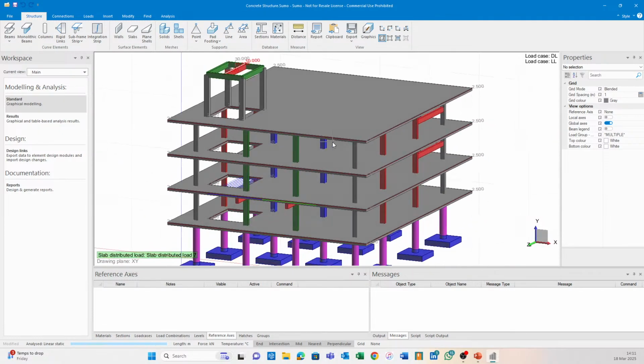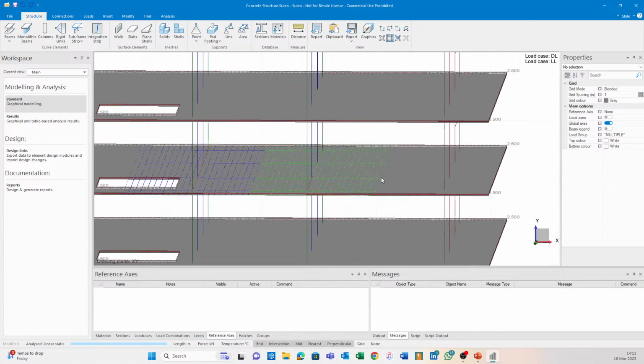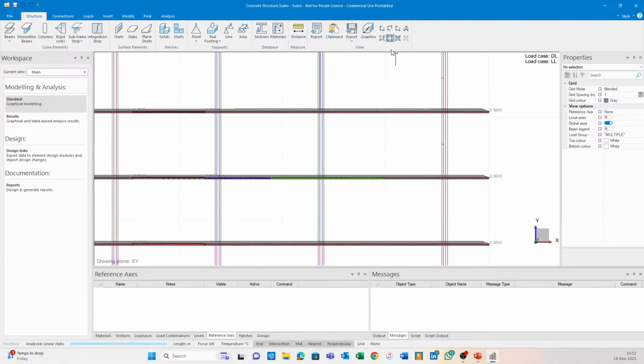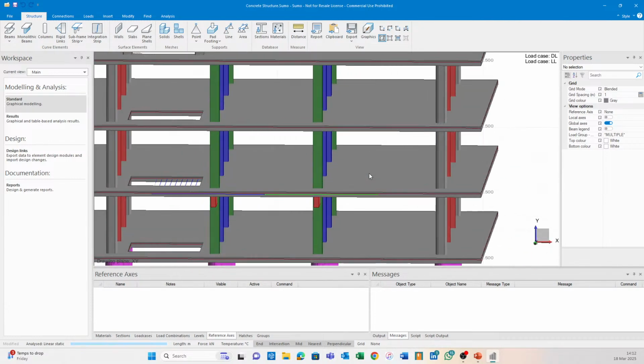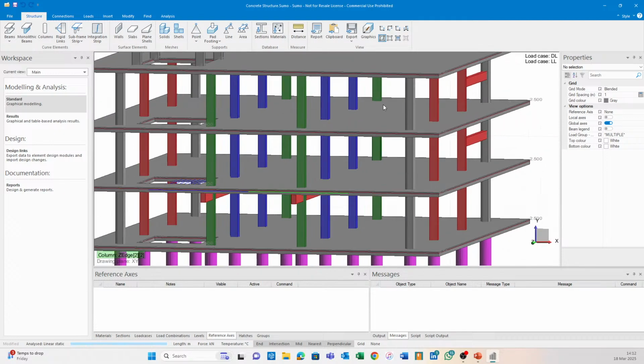Right, now subframe strips are incredibly cool in that they isolate this portion of a slab with all of the relevant geometry within that net, we can say. It isolates all of that, takes it to a continuous beam from where you essentially do your analysis and design from scratch. Very useful for designing things like T-beams, etc.